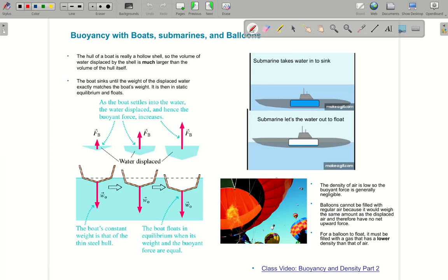Buoyancy is used in submarines and boats, related to the buoyancy of water, or Archimedes principle. For boats, it could be confusing to think about how a heavy steel boat, with a large density, floats in the smaller density water. It is done by making the volume as big as possible, leaving empty spaces in the boat. We can make them displace more and more water. If they displace more water, the buoyancy force applied to them increases, and finally they are able to float.